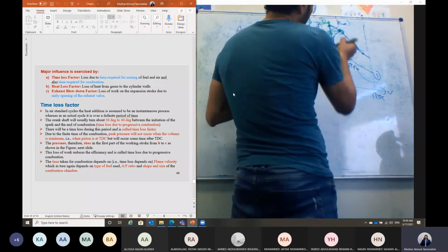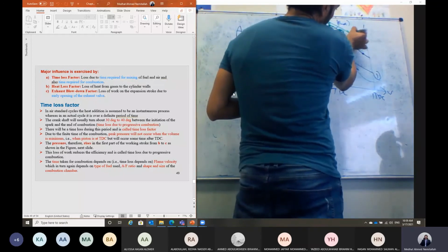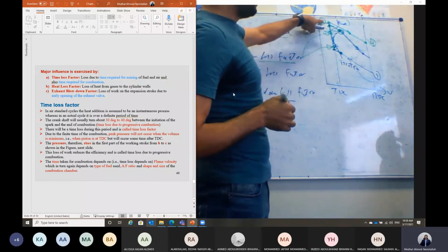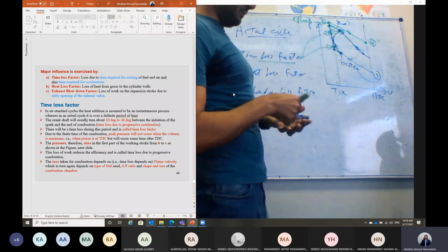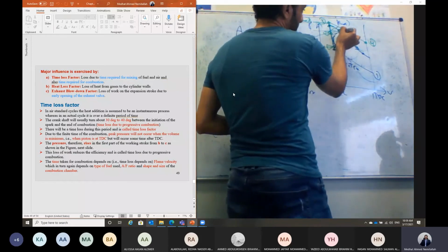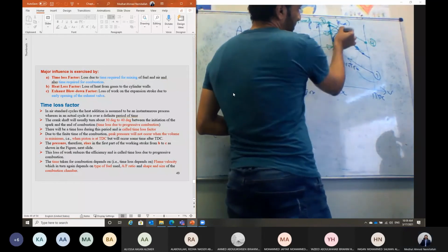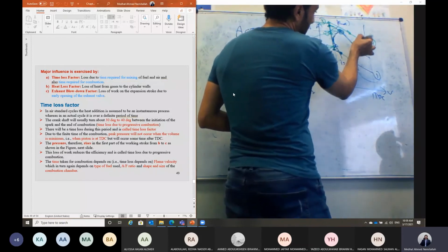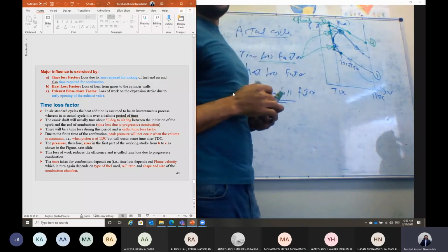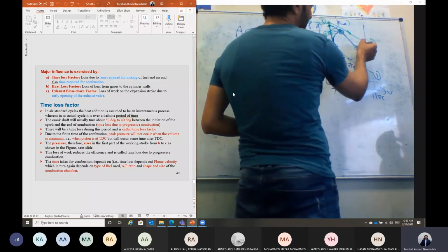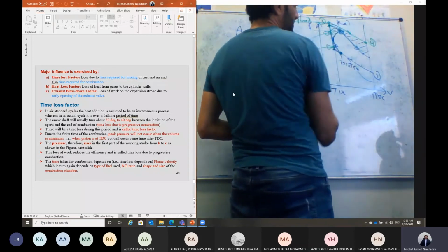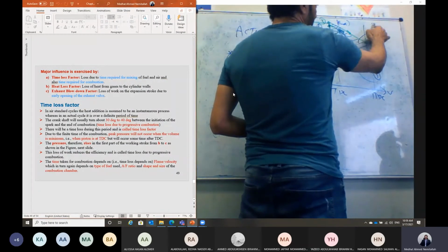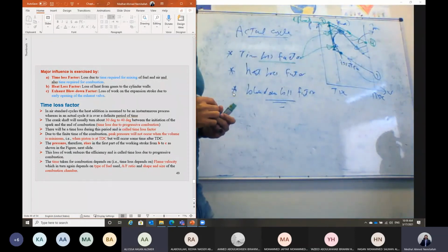If you represent the fuel air cycle, that should be the isentropic expansion from 3 to 4, from the maximum pressure 3 until we reach point 4. But for the actual cycle, this is the cycle. So this is the maximum pressure, and then we should have the expansion in this case. This is the representation of the actual cycle. So there is a difference here, Shabab, in the work also, in the net work. This difference is due to what, Shabab? Let's get from your side.